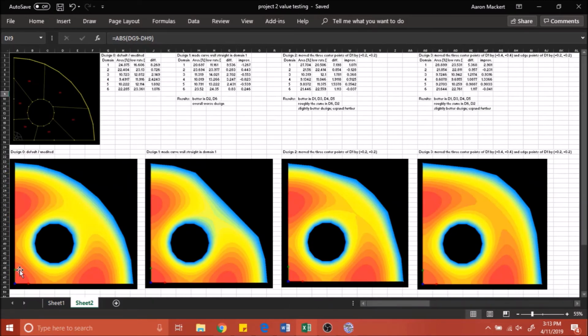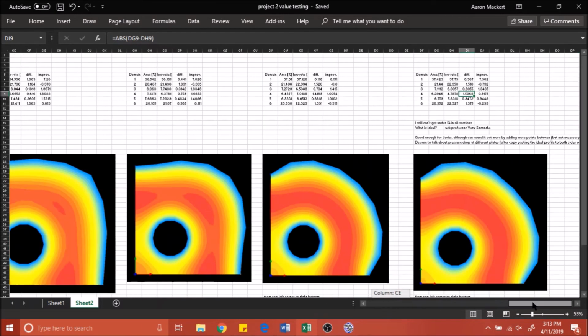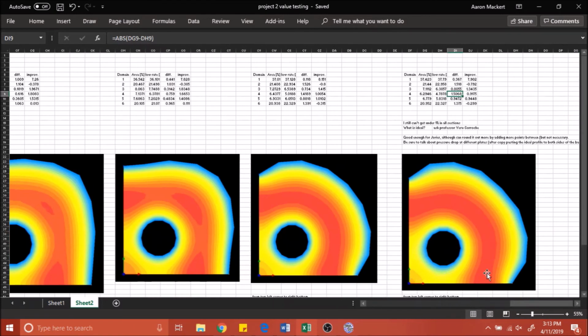If you go back to the default, you can see there's some red here, so it was a little bit more balanced around the circle before, but now it's not. But overall, it's a better design, like an even velocity. Since we can't change this section or this is about as good as it gets without changing the number of nodes that we have. So we kept the same amount of nodes. You could make it look more circular by adding some more if you wanted.